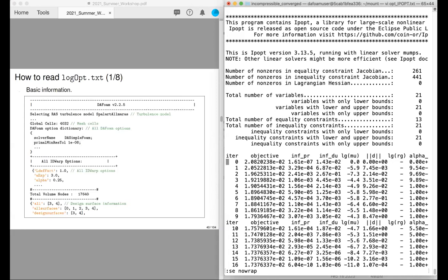Yeah, okay, you're right. By default, the older tutorials I posted online use SLSQP as the default optimizer. That's probably why you don't see this file. IPOPT is also an open source optimizer. We set it in this tutorial mainly because it gives more information. They use different algorithms to do optimization. For SLSQP, the output for this file is very simple. It just prints out the objective function. It does not have the feasibility. It does not have the optimality.